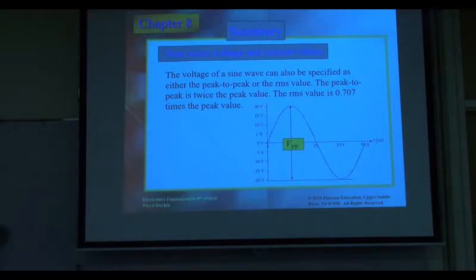This waveform goes up, down, and sometimes zero, while the DC one is constant. If the DC amplitude is also 1, they will not give the same power, because the DC is constantly 1 while the AC is 1 at maximum, sometimes 0 and sometimes in between. So the AC gives less power. What DC value gives the same power on the same load? That is 0.707, or more accurately square root of 2 divided by 2, approximately 70%. So if the peak value equals 1, we need 0.7 volt of DC to give the same power.